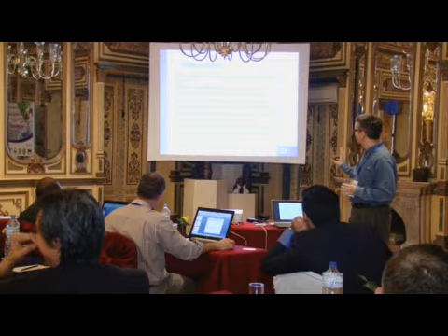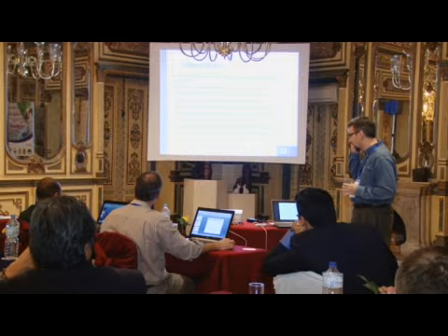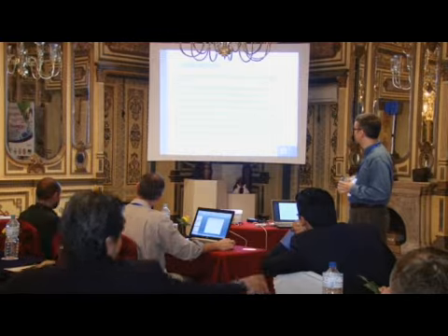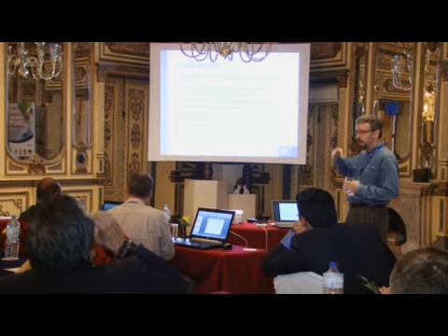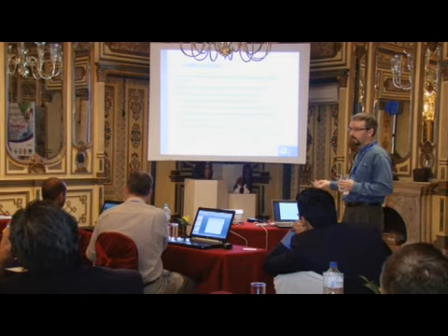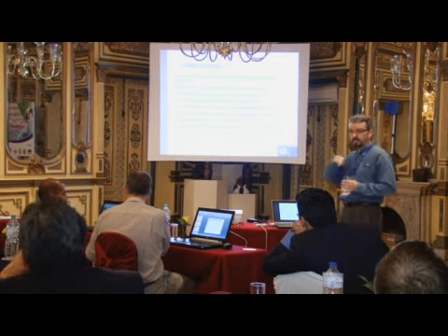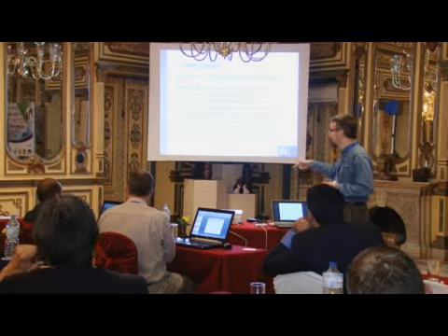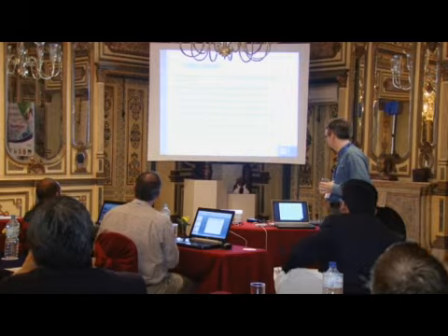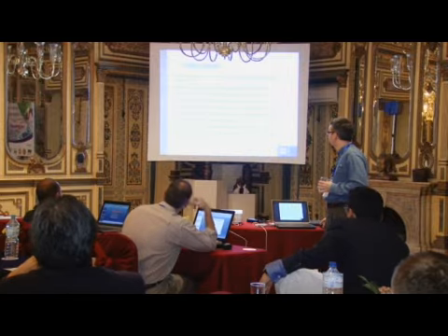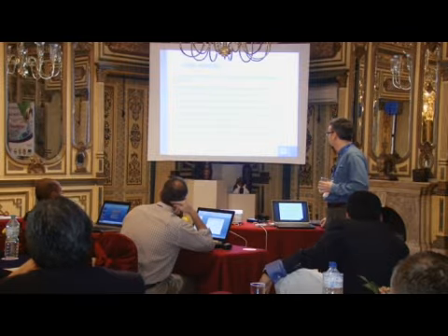So these are overall conclusions. A lot of this is common sense, but it was nice to go through the exercise and understand these different aspects. So we need a good framework within an organization that wants to be energy neutral in order to make it work. That means you need to have champions within that organization that will drive things, otherwise things won't happen and you won't get anywhere near energy neutrality. In terms of best practices for energy use, the one that jumped out massively was the need to maintain your fine bubble diffusers if you have them.